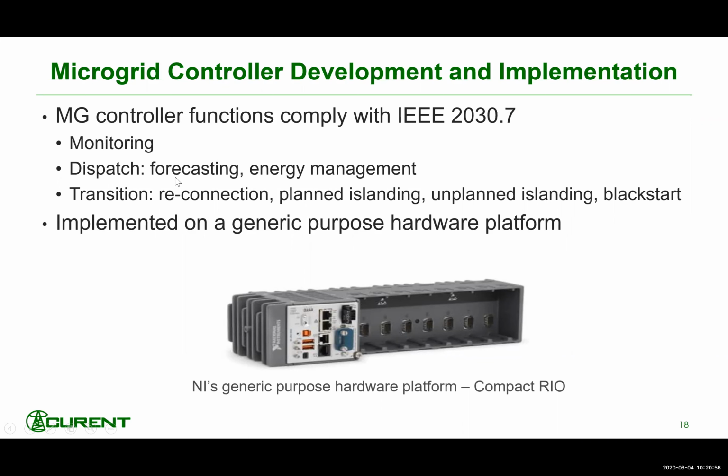During the steady state mode, either grid connected or islanded mode, we can do monitoring, forecasting, and energy management. For example, we can determine when we need to charge the battery and when we need to discharge the battery, for example, for peak load reduction.